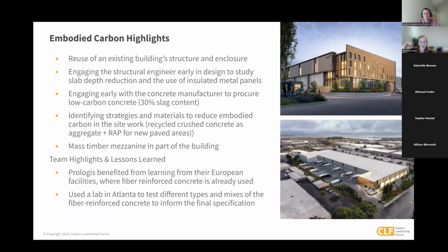They needed additional height in some of the spaces, and so they used 6-inch insulated metal panels instead of concrete, which allowed them to extend the height of the wall to build on the existing buildings, and also to not add any additional foundation or wall support that they would have needed if they extended the height with concrete.